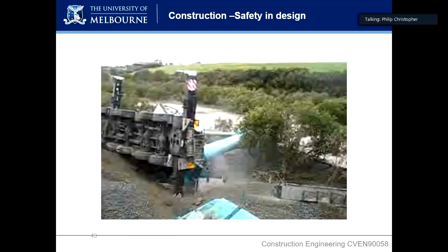Other examples of failures like this is when cranes are lifting on a superstructure, so on a bridge itself, and those outriggers just punching through the deck of the bridge can be an issue as well. So really important in your task for your specifying construction sequence. So I think probably saying, you know, assessing and designing for a crane pad would be an appropriate thing to be recommending in your design.